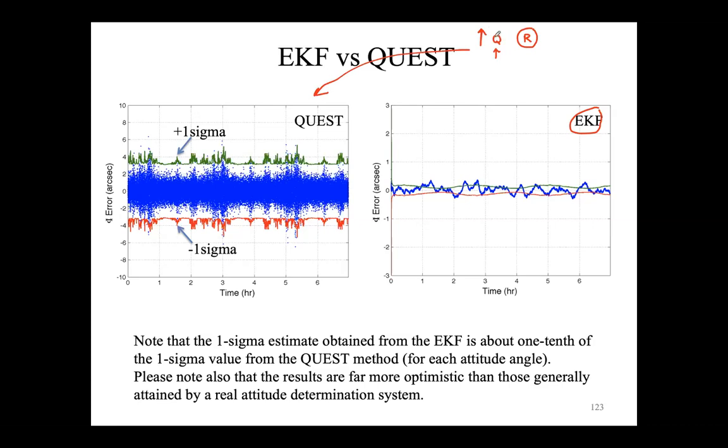So you have to find a value that is not inconsistent with R. Of course it will be larger, because you know that the accuracy of the gyroscope is lower. But you have to find a value that enables a good convergence. If you find a good compromise, this is the tuning: you iterate your values of Q in order to see what is the best response in your filter.